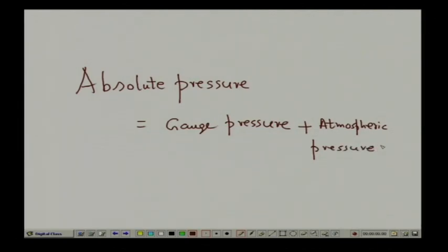Typically this U-tube manometer looks like the English letter U, that is the name we have coined for it, and I should say it is one of the oldest pressure measuring devices mankind has developed. Still it is used as a monitoring instrument in many process industries, for estimating pressures in bioreactors, in the laminar hood or in the actual process.